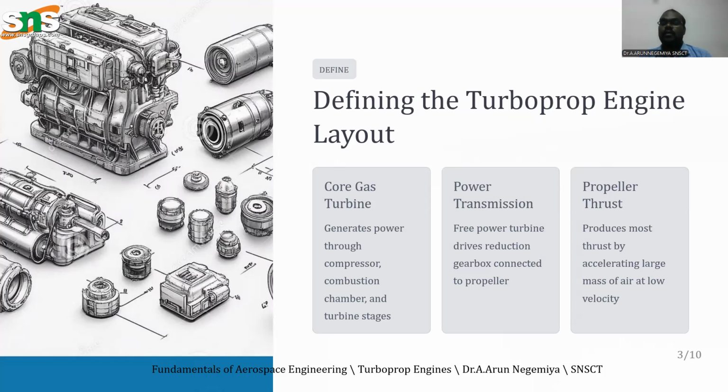The compressor is useful to compress the air, and that air comes from the suction part: the propeller sucks the air and allows it inside, and it passes directly through the compressor. Next one is the combustion chamber. The compressed air travels from the compressor to the combustion chamber. Here the fuel is supplied to the combustion chamber area. The fuel mixes with hot gases and the burning happens.